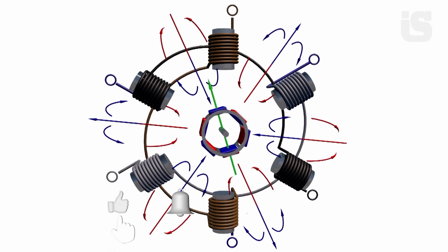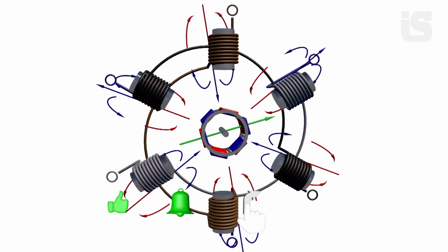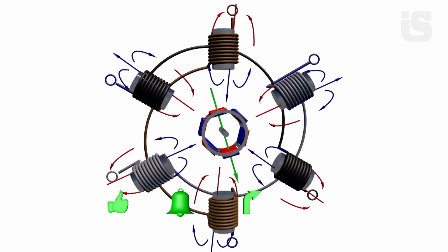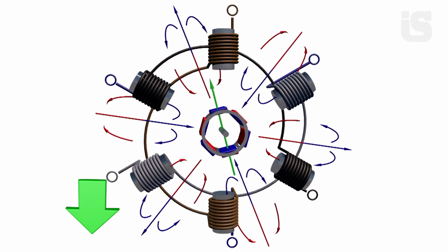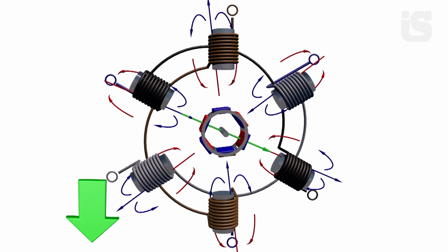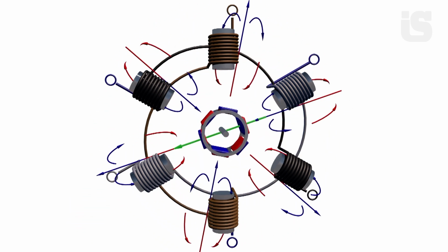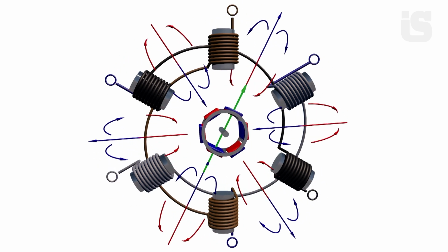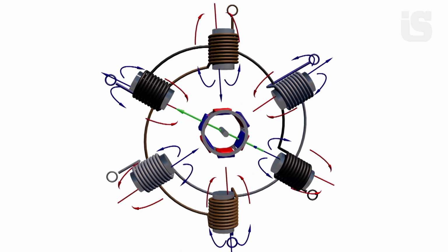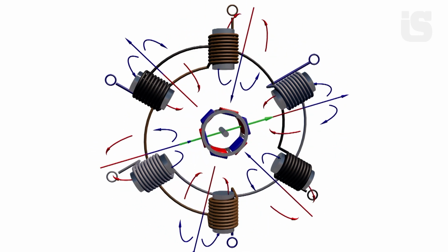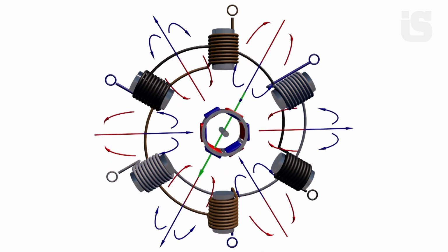The Squirrel-Cage accelerates the rotor's rotational speed, and the permanent magnets can now interact with the rotating stator field normally. The rotor's rotational speed equals the stator field's rotational speed. The Squirrel-Cage does not function in this case, because the frame itself will not intersect the magnetic field lines.